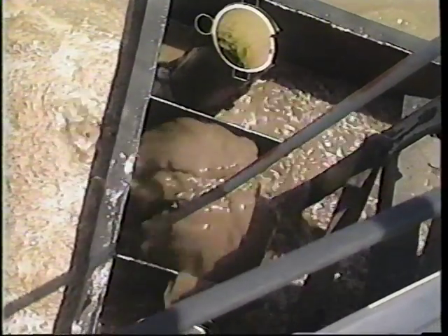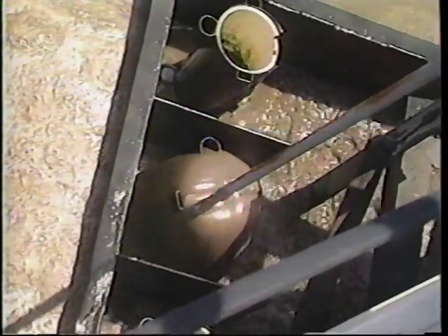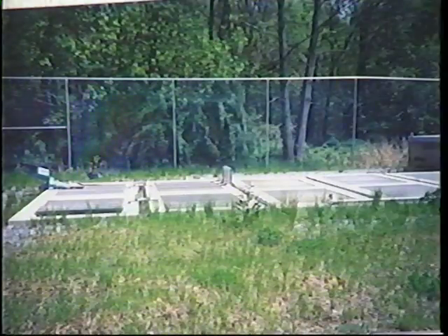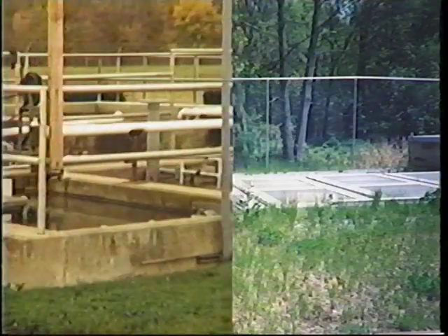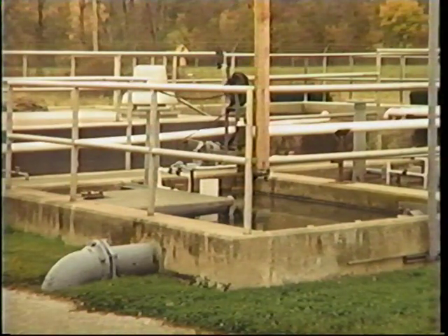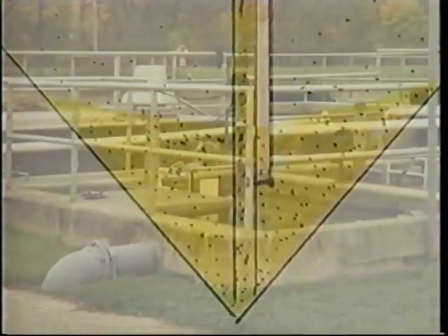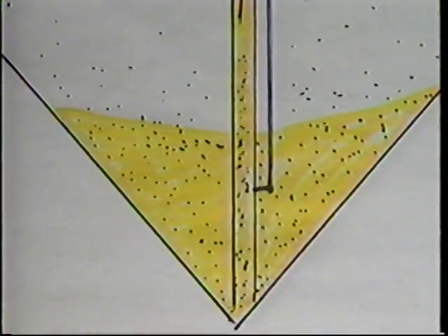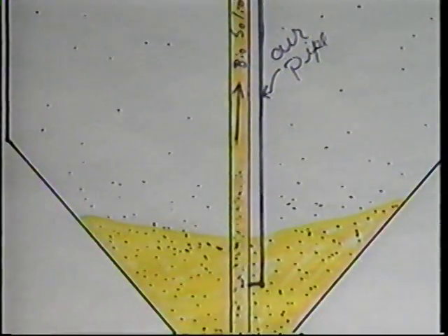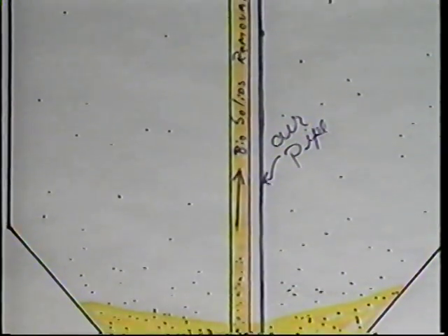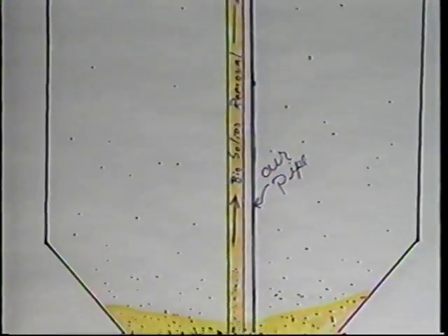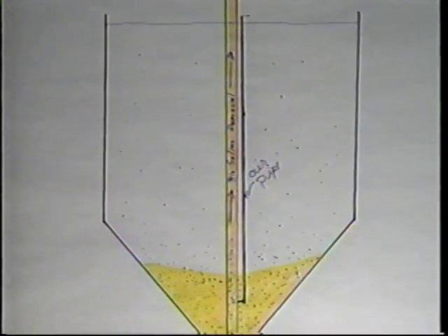As with rectangular clarifiers, you need to pay close attention to details such as solids removal rates, scum removal, and the effluent weirs. You may also see very small square clarifiers in package-type treatment plants. These clarifiers usually do not have a sludge collection mechanism, and the tank slopes into a very steep-sided hopper where the sludge is removed. Typically, both sludge and scum are removed with an airlift type of solids pumping system.